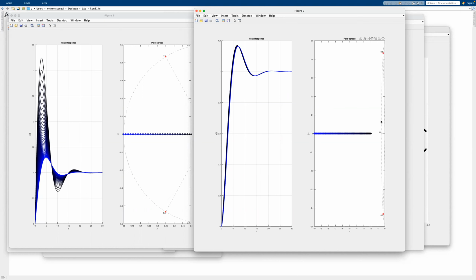That forms your pole pair. You decide on two of the poles. All the remaining poles need to be pushed away, and if you have more than one solution, you look for the best in terms of dominance. If not, then you have just one choice and you go with it, or maybe you change your controller.